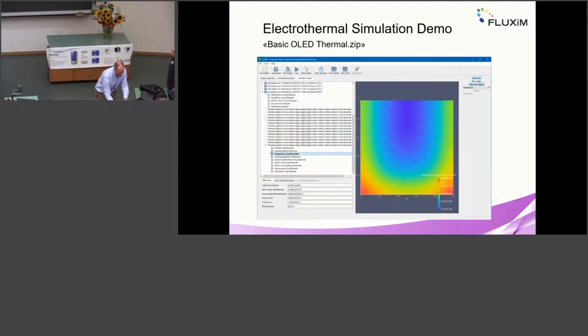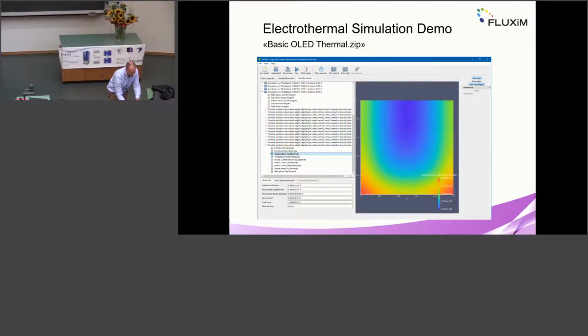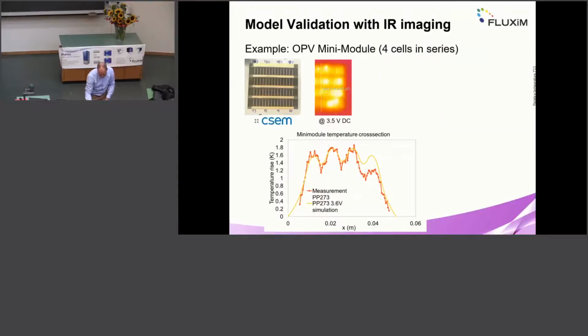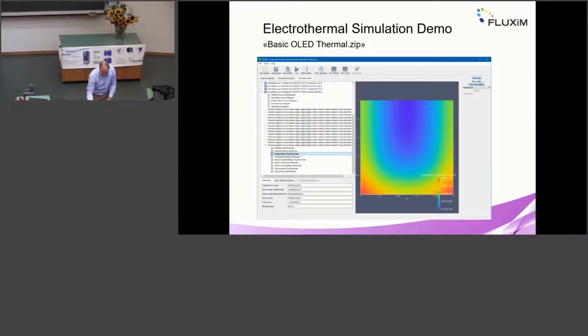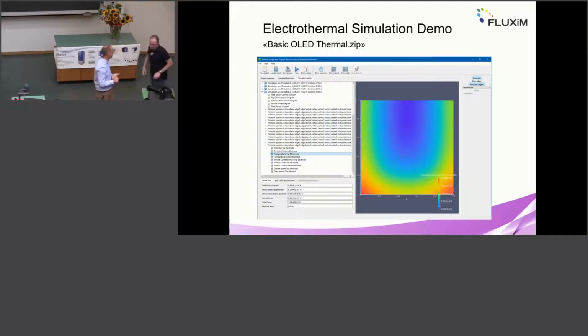And in the boundary conditions, in the thermal modeling, you also need to care about how the heat can escape vertically, on the top surface and on the bottom surface. There's a heat transfer coefficient describing how heat is transferring, or it may be a radiation law as well. So these are typical properties of thermal boundary conditions.